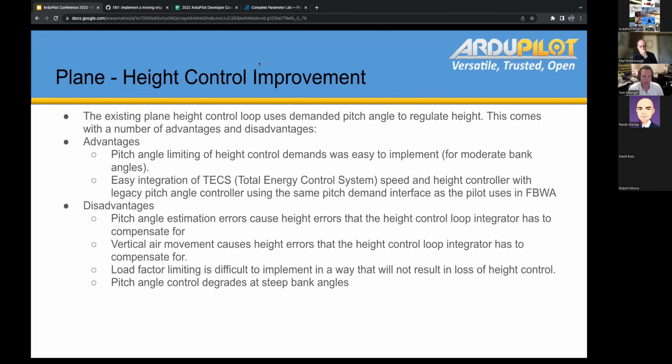At Krauss and Downey Aerospace, we actually did some testing of dead reckoning for a while on fixed wing, and this is on EKF2, but we were getting fairly consistent, a linear drift of about 1 meter per second. We could do that for 20 minutes at a time, and the whole thing would drift linearly, but it was more about a wind error. So I would think more about a wind estimation error, but yeah, it's surprisingly stable though.